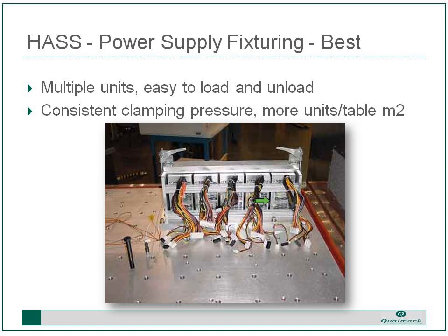That was something you need to worry about when you start putting multiple units in a chamber: am I going to get enough airflow through them to get the ramp rates I need on the product? So that's an important piece to keep in mind. And in this case, we could get them pretty close together and still get the ramp rates we needed to get.